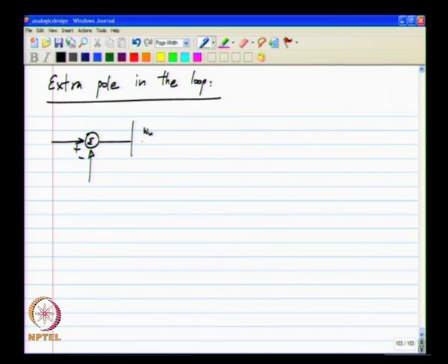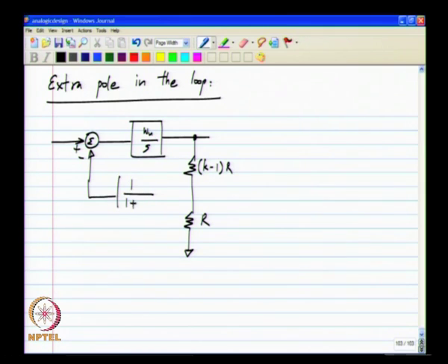our usual system, an integrator with a unity gain frequency omega u, a voltage divider of fraction 1 by k, and here I will simply have an ideal block which models the pole. Okay. Just like the delay, it does not matter where in the loop this pole is. So, as long as it is in the loop, it will affect the response of the system.